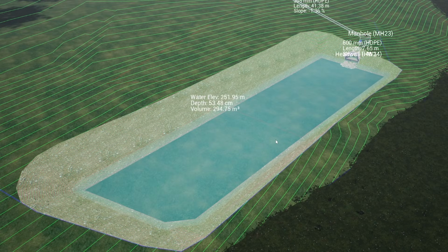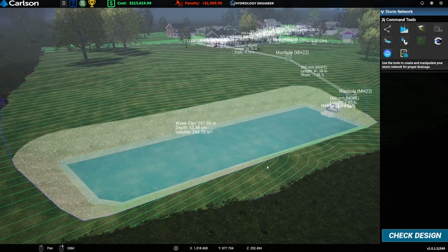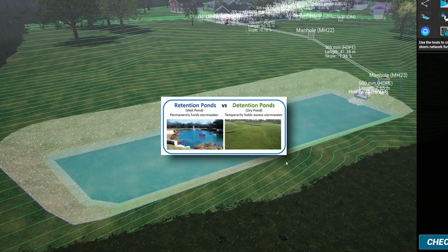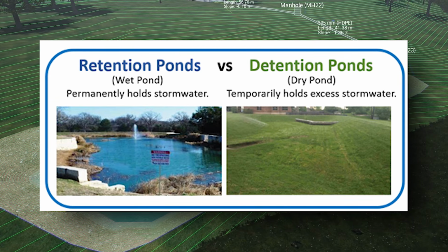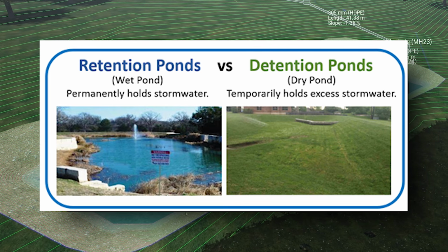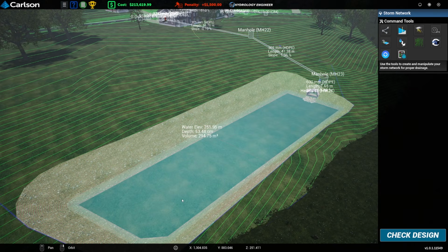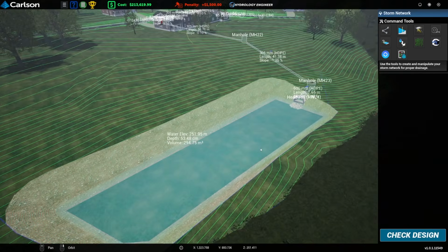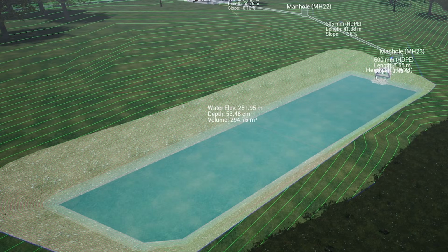That's compared to what we call a detention basin or a retention pond, where basically they just store water to allow us to limit how much comes out. And if you want to get into details, the difference between a detention basin and a retention pond is a detention basin is usually dry most of the year, but when it rains it fills up with water. A retention pond is usually wet the whole year round. They all have different benefits. This one, because it's an infiltration basin, is probably more likely to be like a detention basin, so it will be dry most of the time apart from when it rains, because remember the water's meant to infiltrate into the ground, so you want this to be dry unless it's just rained, really.